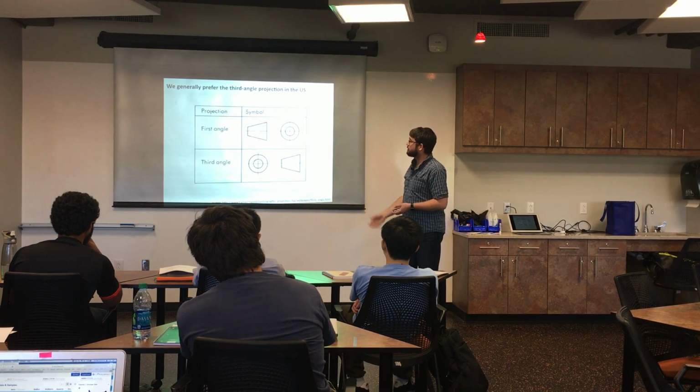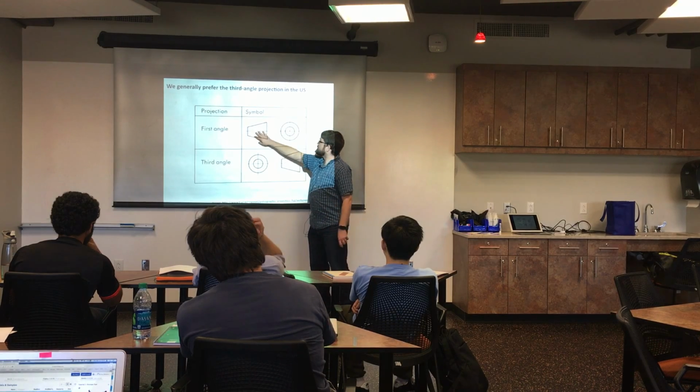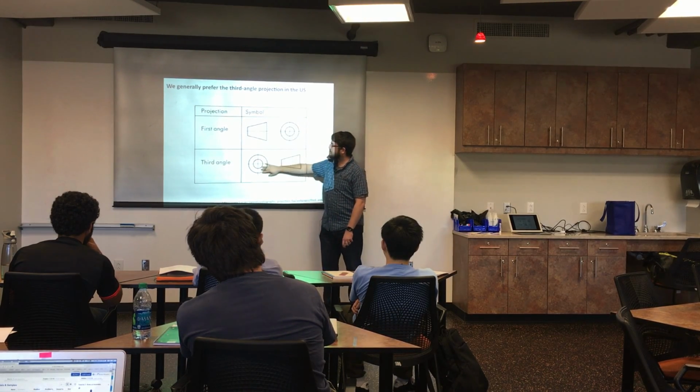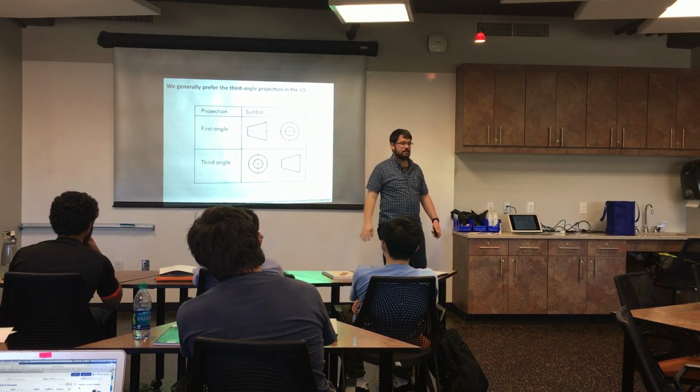So a quick way to tell if it's first or third angle is in a first angle drawing, the view will be to the right. In a third angle drawing, the side view will be to the left.